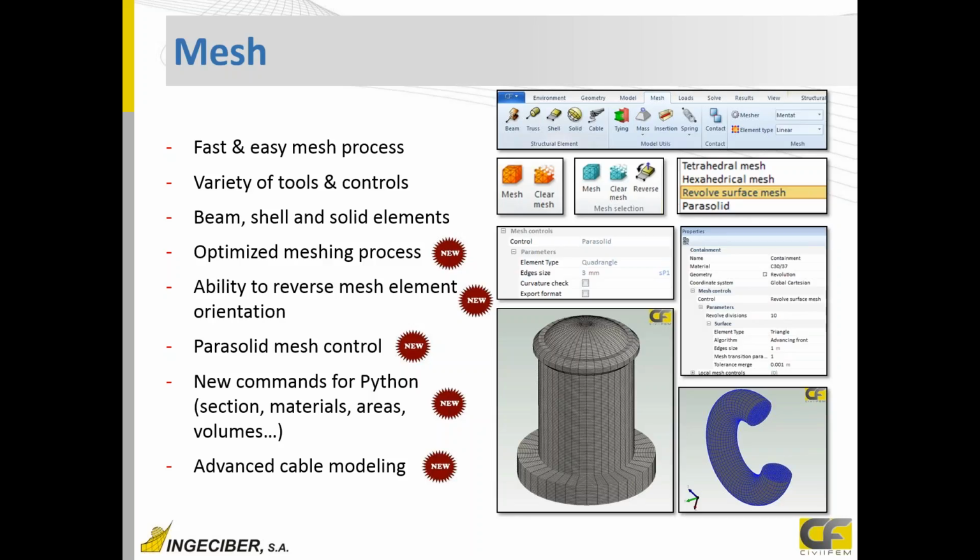If we need to do that, if the results do not please us, we can reverse, for example, the direction of our axis, in the case of reinforcement amount results, or for contact analysis. Sometimes we have to reverse the direction of some axis of the elements which will be in contact.